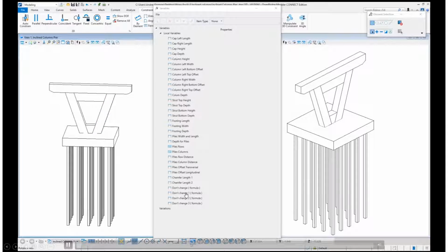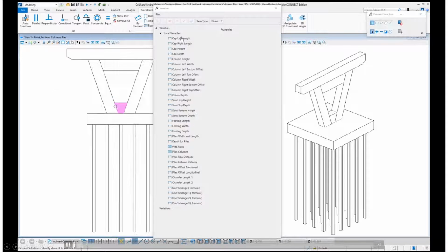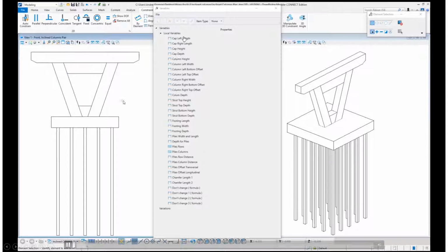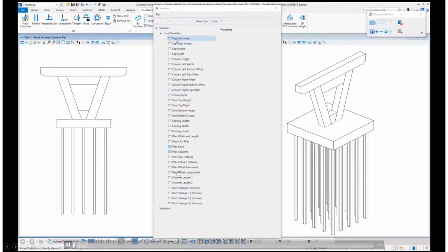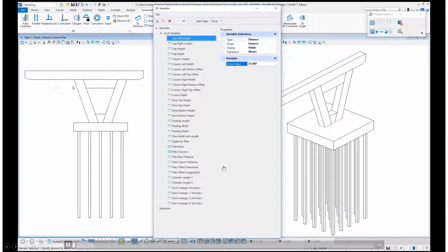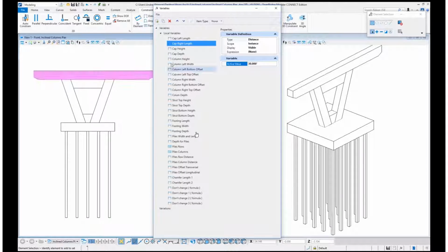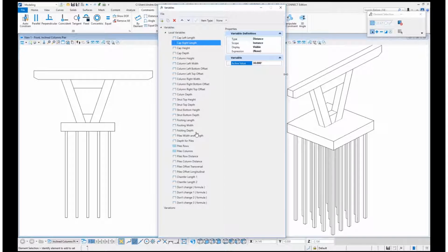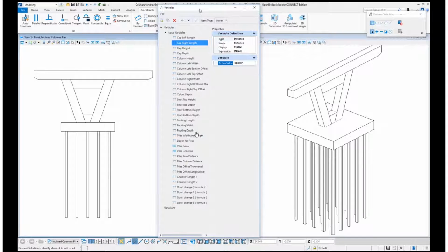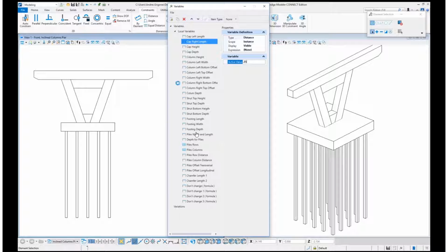And then, don't get me wrong here. We set it up in such a way that it will try to accommodate every single variation of the library, from the cap all the way to the piers. But you don't need to do all these variables unless you really want to make it fully parametric. So don't go overboard on trying to define every single element as parametric. Do it as practical as you may consider, depending on what in your pier will change.